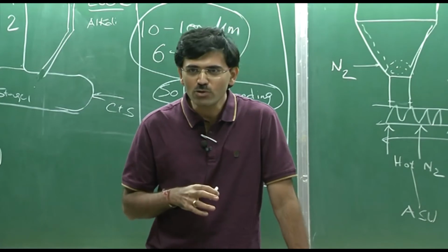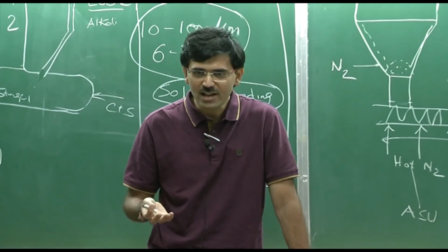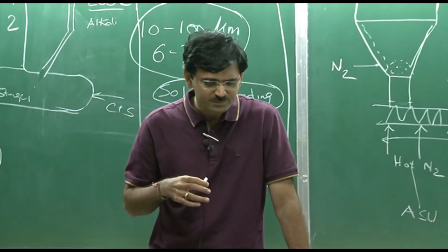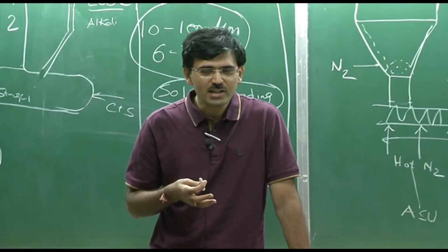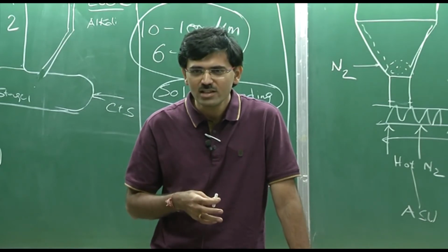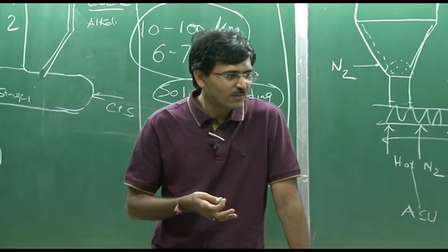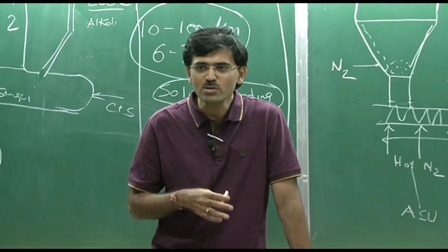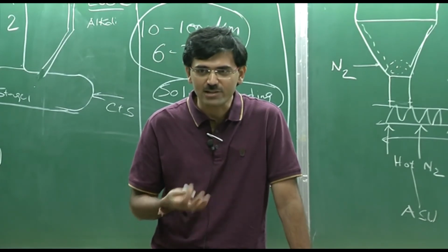Whatever flue gas is produced by a CCGT, the idea was to separate carbon dioxide from it. But this CCGT produces only something like 3-4%, 5% carbon dioxide, or larger units may produce a bit more. A natural gas powered gas turbine does not produce much carbon dioxide in the flue gas; it is much leaner.